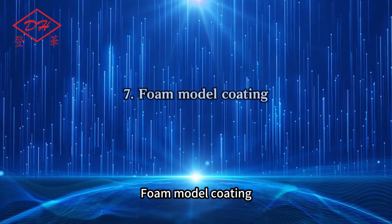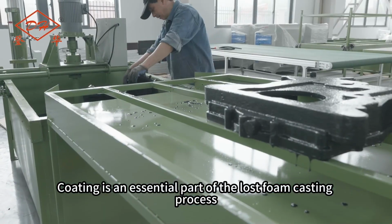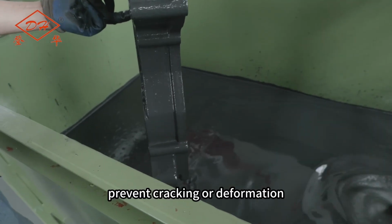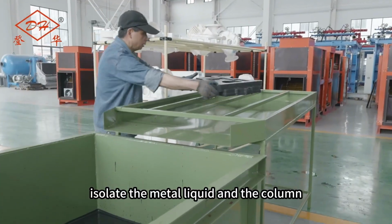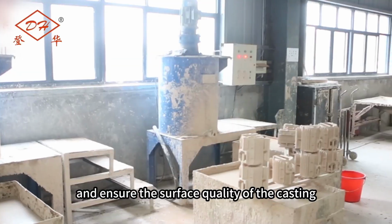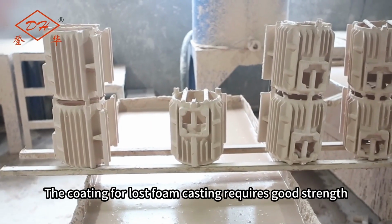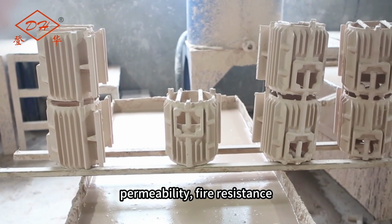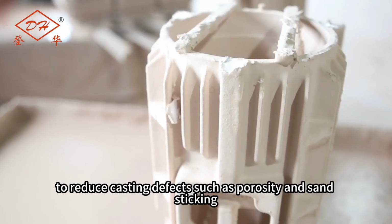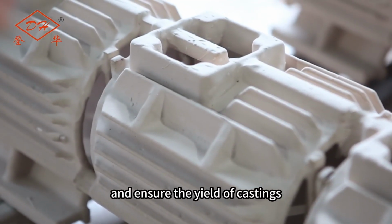7th. Foam model coating. Coating is an essential part of the lost foam casting process. Its main function is to increase the strength and rigidity of the model, prevent cracking or deformation, isolate the metal liquid and the sand, remove the gasification products of the model, and ensure the surface quality of the casting. The coating for lost foam casting requires good strength, permeability, fire resistance, coating properties, suspension, and one-time shedding, etc. to reduce casting defects such as porosity and sand sticking, and ensure the yield of castings.